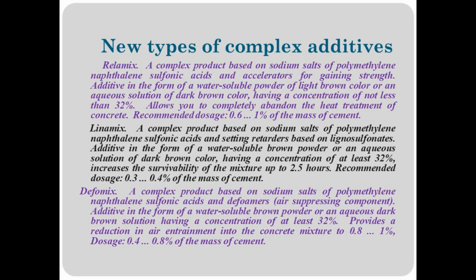Provides a reduction in air entrainment into the concrete mixture to 0.8 to 1%. Dosage 0.4 to 0.8% of the mass of cement.